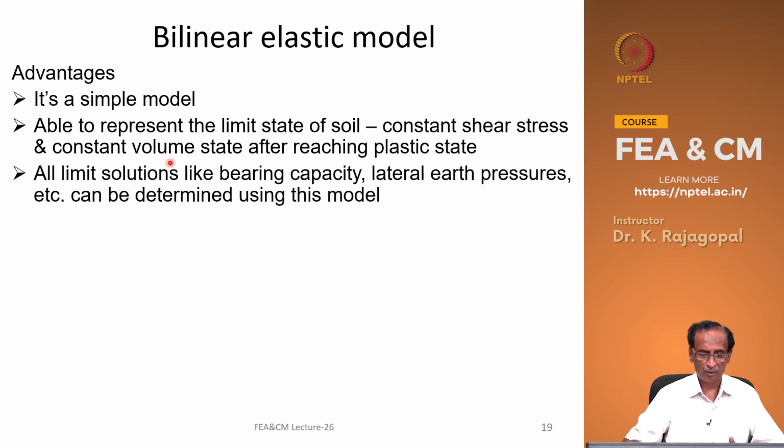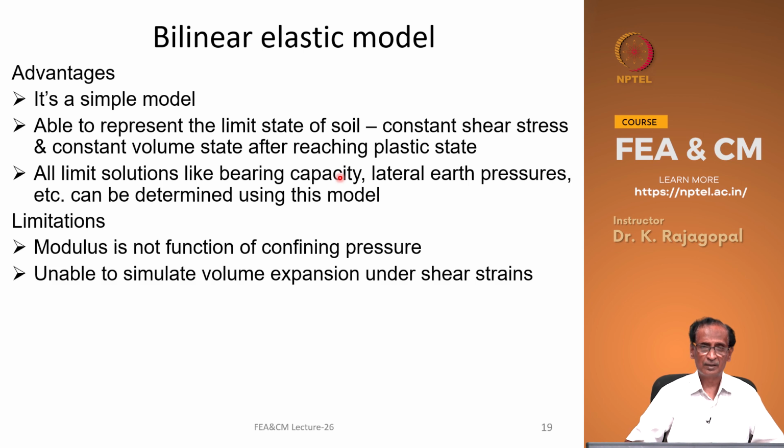And all the limit solutions like our bearing capacity or the lateral earth pressures or the factor of safety of the slope against the slip circle failure, we can simulate by using the simple bilinear elastic model. But the limitation is the modulus is not a function of confining pressure.